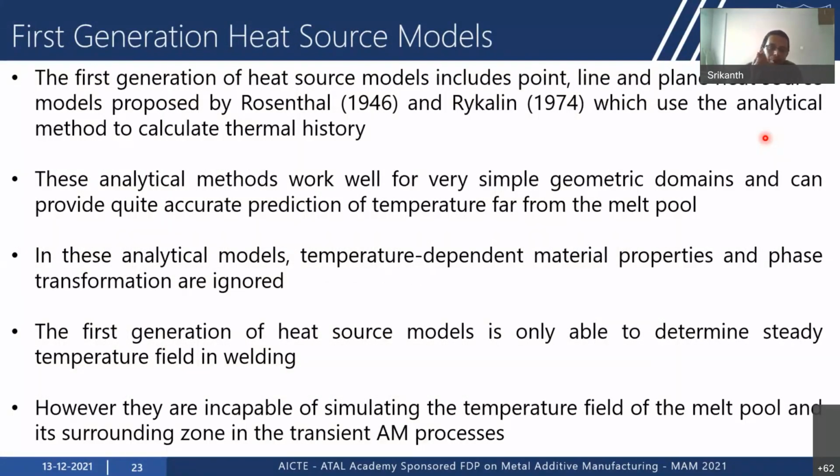So the next one is, how do we capture the input from the heat source? When the first metal AM processes were developed, to understand the effect of process parameters and the characteristics of the deposit, people visited the literature to understand what different types of modeling techniques are available. And they particularly went back to the welding literature, because metal AM is nothing but multi-pass welding. So the first generation of heat source models essentially used analytical methods to calculate the thermal history.